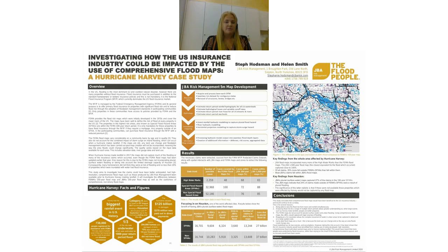At JBA Risk Management, we've created river, surface water and coastal flood maps at a 5-metre resolution for 6 return periods: the 20, 50, 100, 200, 500 and 1500-year flood. We take time to prepare our input data and then use our in-house 2D hydraulic model, JFlow, to capture river and surface water flood, as well as horizontal projection modelling to capture the storm surge hazard. We then use iterative GIS techniques to process the hydraulic model outputs to create seamless flood depth layers for the 6 return periods.